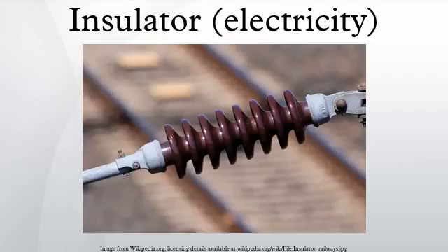However, for high-voltage transmission lines, strings of cap and pin insulators are used, attached to the cross-arm in a horizontal direction. When the tension load in lines is exceedingly high, such as at long river spans, two or more strings are used in parallel. Shackle insulator.